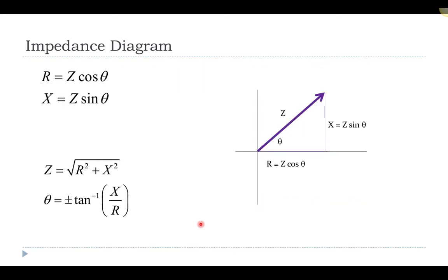Everything we've talked about so far we can still use. Our impedance diagram is also still valid, so we can figure out the total impedance in the circuit by adding the resistive piece and the reactive pieces squared, taking the square root. What we're going to find is that in our circuit, if we have a capacitor and an inductor, one of those two components is going to actually dominate in the end in terms of our end result. So everything we've learned so far about impedance diagrams is still valid. We're just going to add another piece to this in terms of having multiple components.